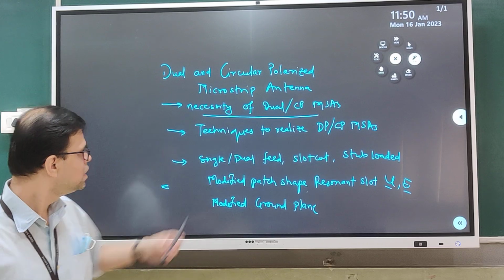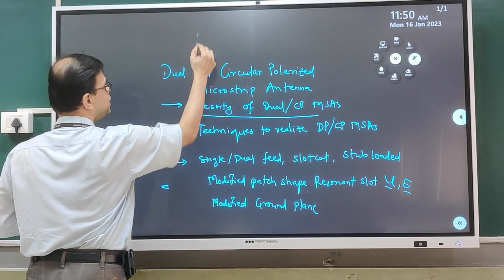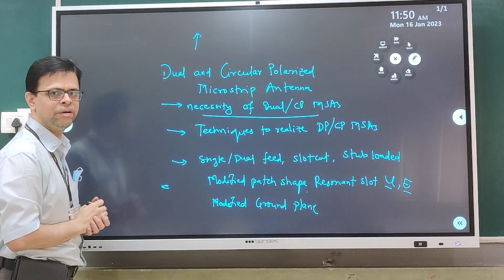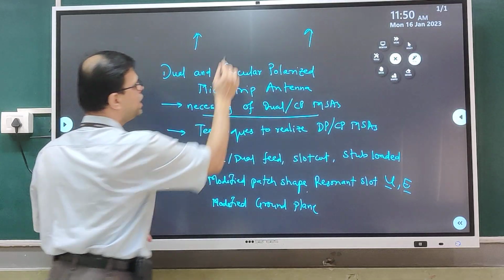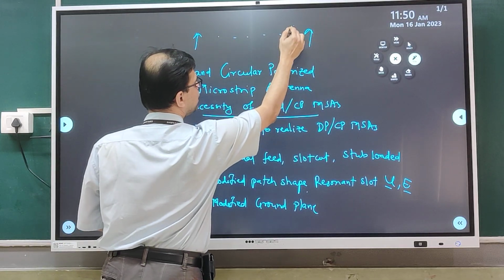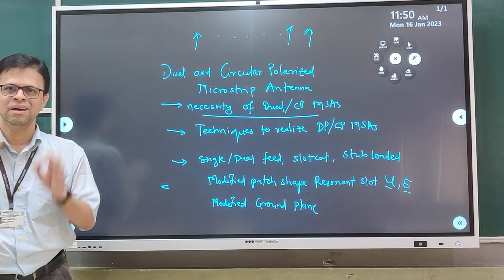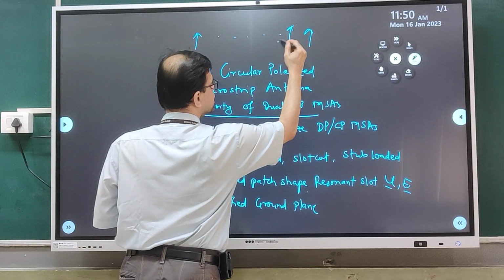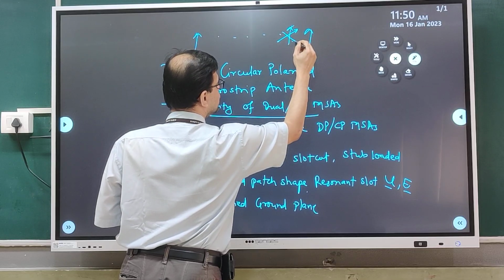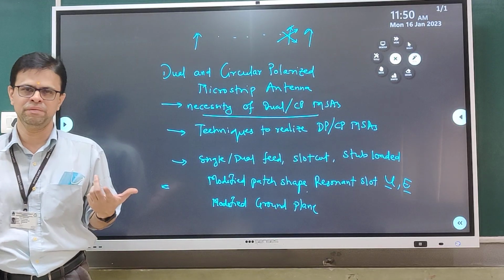So once a signal is transmitted from a transmitter, you cannot guarantee that at the receiver you will get an effective vertical polarized signal. That may have gone across different changes and the polarization would have become something different.